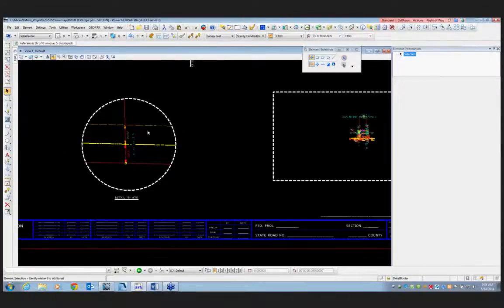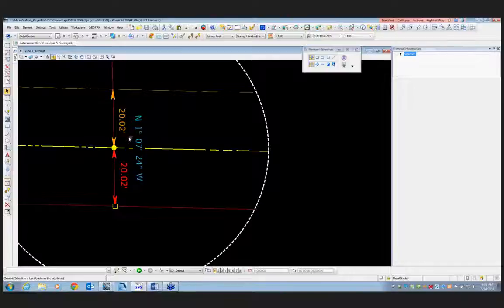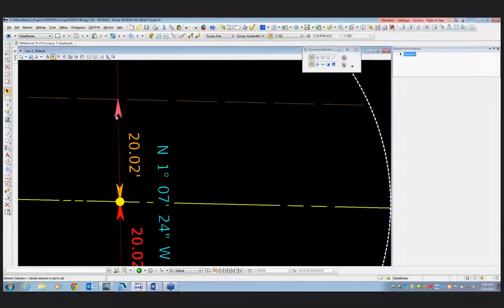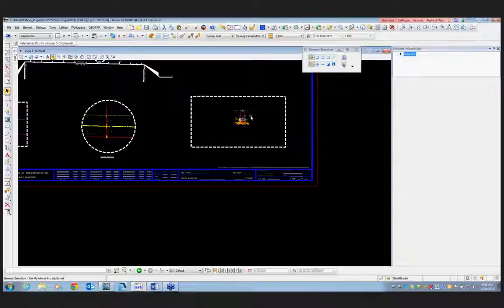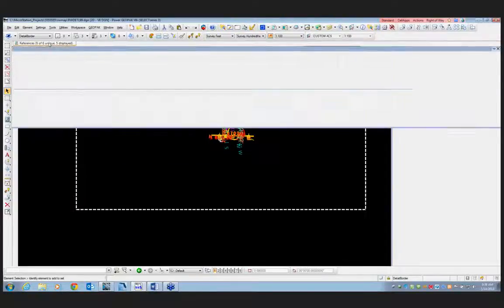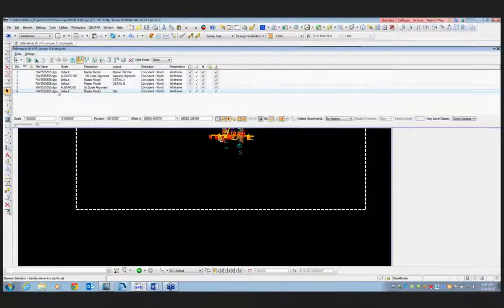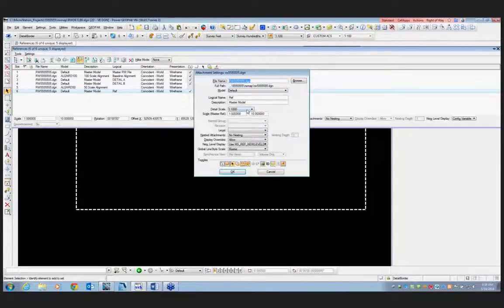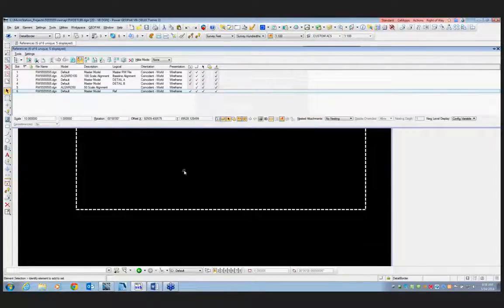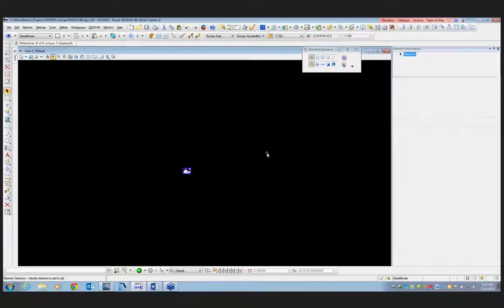Instead of setting it at 1,000 or 2,000, I just set this to 20. The arrows automatically change. I could actually change this in the file to something more reasonable, and I want to do that, just give you a taste of what that would be like. I'll change it to something like 1 inch equals 10 feet, say OK, and note that it disappeared again. What it has done is it's moved because of the scale. In this case, it moved up northeast of it.